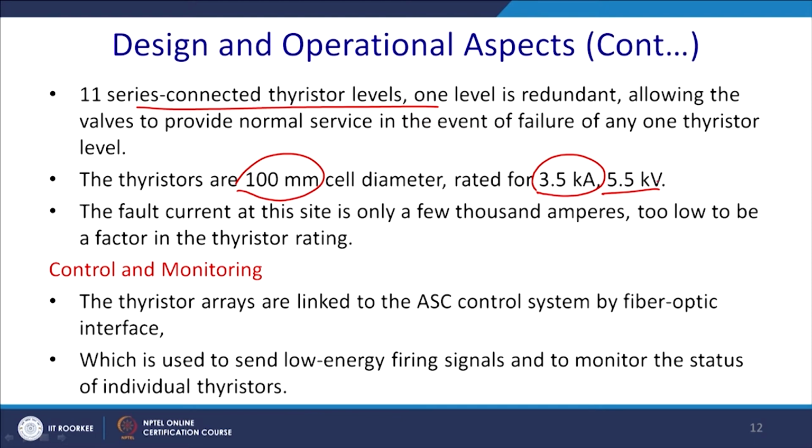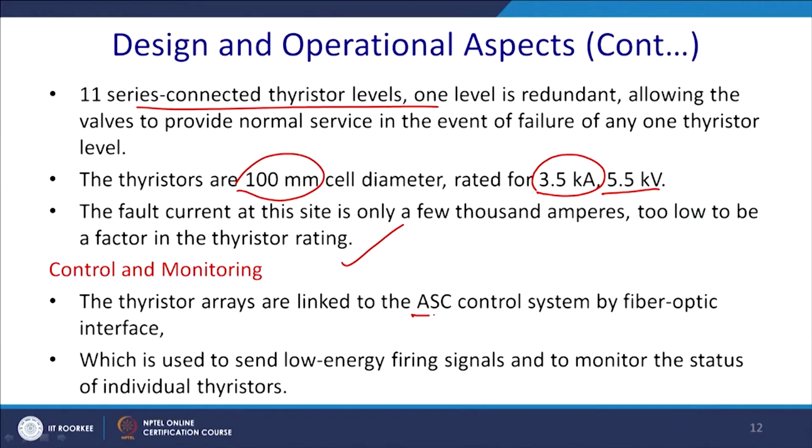The fault current at this site is only a few thousand ampere, too low to be a factor in the thyristor rating. So, this is one of the reasons that FACTS devices can be placed and the cost of the FACTS devices does not increase. The thyristor arrays are linked to the advanced control system by fiber optic interface, which gives you the required isolation, and that helps you to operate from a distance also with SCADA or another interfacing requirement, which is used to send low energy firing signals and monitor the status of the individual thyristors.